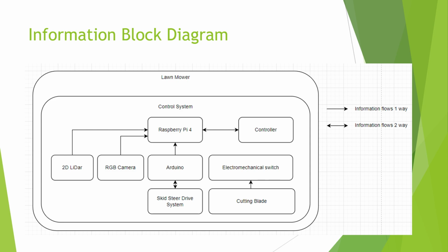The Arduino is totally handling the encoder sensing and also the drive. So it's doing pulse width modulation on the 12-volt motors, so it can reverse the direction of either side of the mower, and it can slow down and speed up, and do all the things you'd expect an autonomous mower, or autonomous drive system, to be able to do. So it can vary the speed, it can vary the direction, and it picks up the counts from the encoders on the motors.